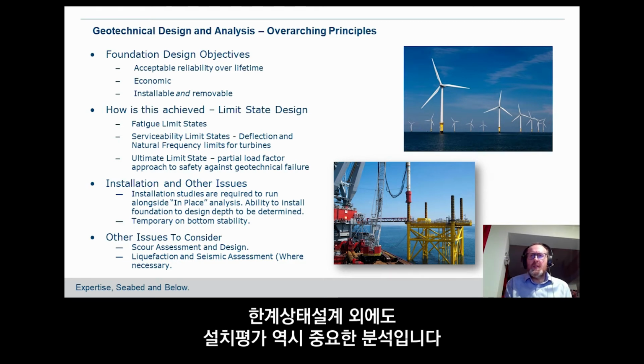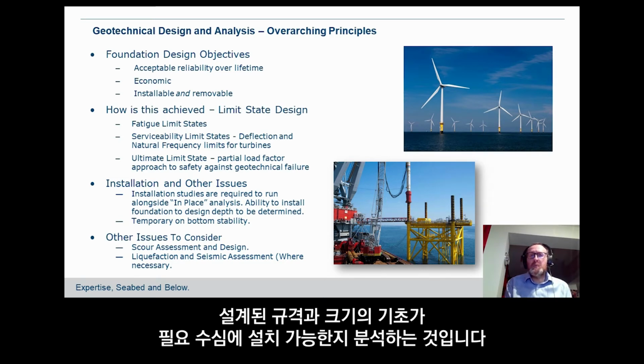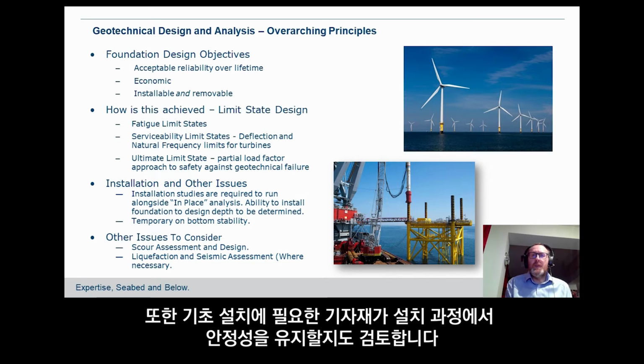As well as the limit state design, we also have to look at the important issue of installation. So we carry out specific installation studies to check that the required foundation dimensions can be installed to the required depths or the sizes that can be produced, and that the equipment that needs to be used to install those foundations will be stable during the installation process.